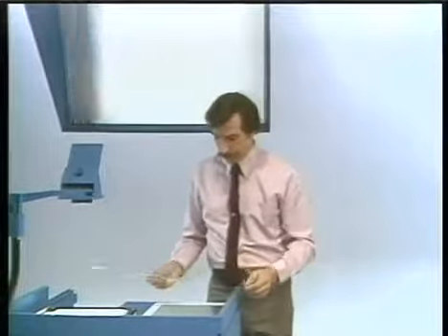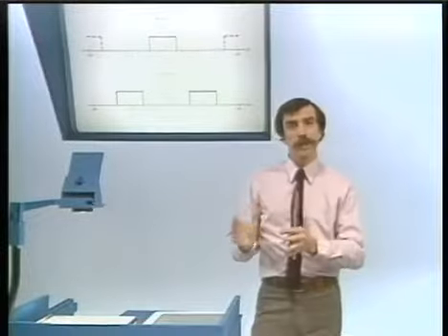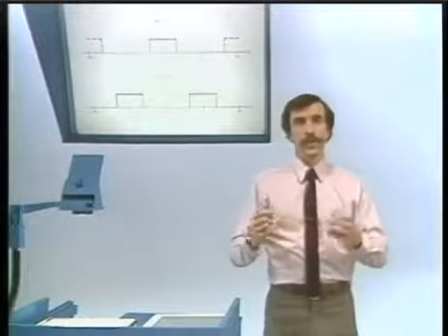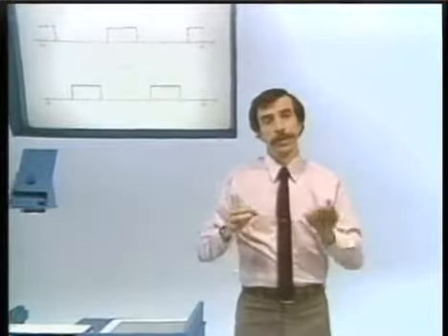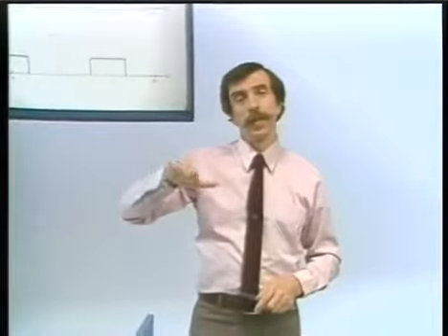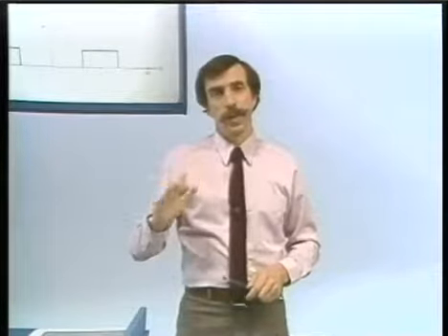Well, just as we talk about a low-pass filter, we can also talk about a high-pass filter. And a high-pass filter, of course, would pass high frequencies. In a continuous time case, high frequencies meant frequencies that go out to infinity. In the discrete time case, of course, the highest frequencies we can generate are frequencies up to pi. And once our complex exponentials go past pi, then, in fact, we start seeing the lower frequencies again.